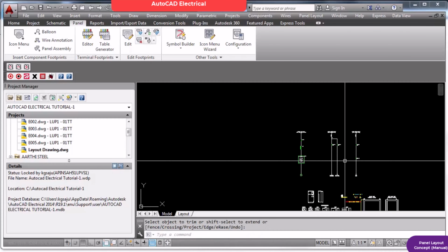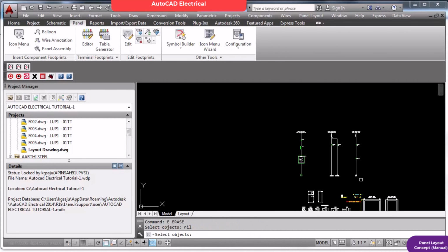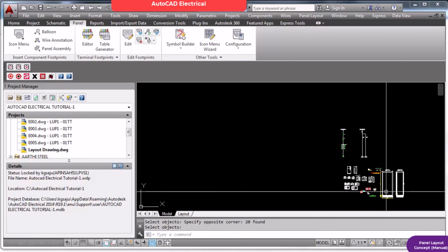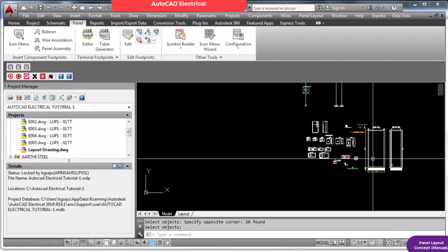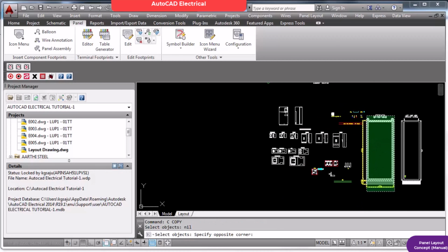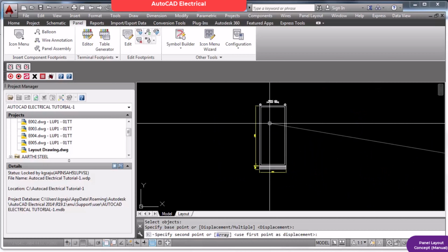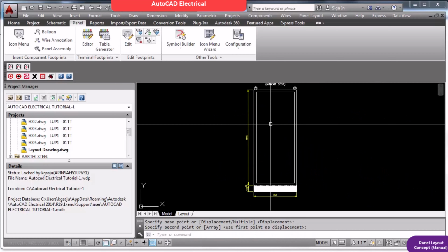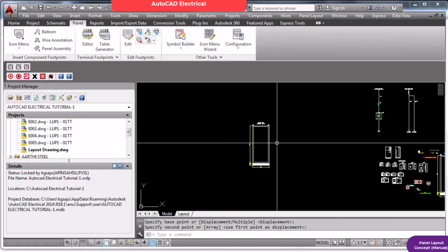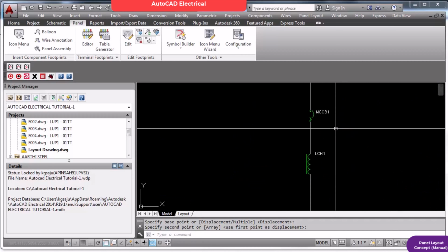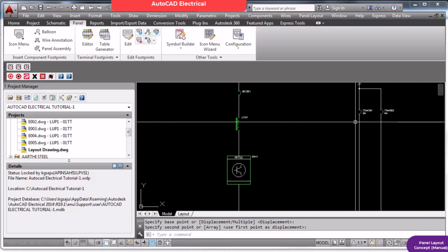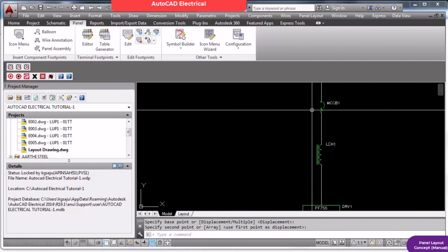So from my library, I have copied all the blocks which are necessary for me into a single sheet, including the panel. Now I will create a drawing in this sheet, keeping all the blocks aside. This is the front view of my panel without a door. Now I have to place an MCCB, line choke, drive, and 2 MCBs. That's all.